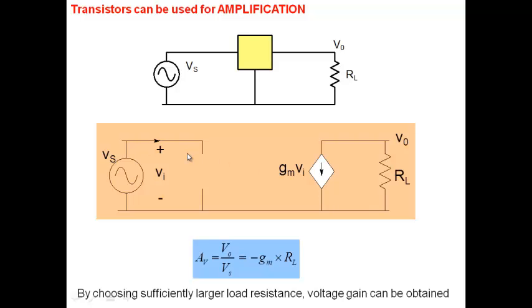Input is an open circuit. Where is all this power coming from? So it's just a hypothetical ideal element. It can't exist. There's no source of power, and it violates the law of conservation of energy. So no element can be like this, an ideal voltage control current source.